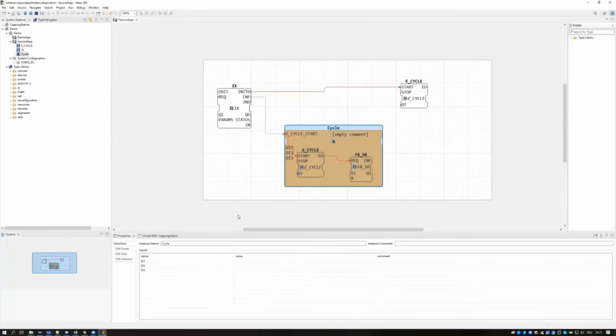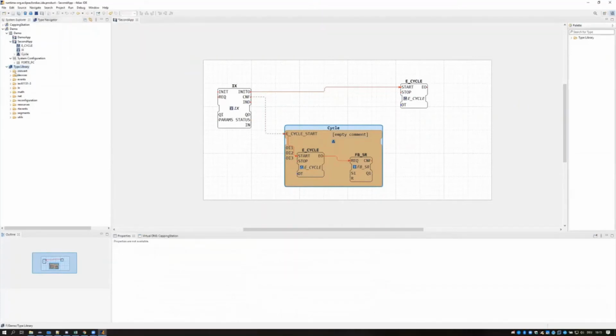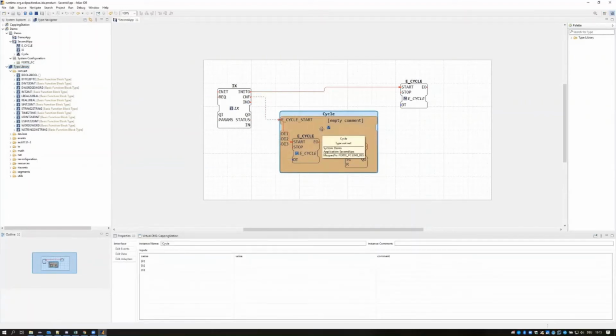Sub-applications can be untyped or typed. In our ForDiag project, we can find a type library where all types are listed. Typed sub-applications are stored in this library and can be used in an application. Untyped sub-applications are mainly a mechanism for structuring applications. They can easily be edited within the application via the property sheets and are only available in the application.